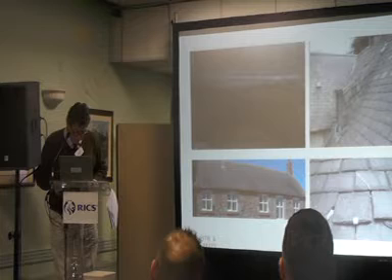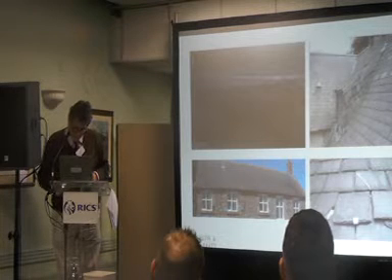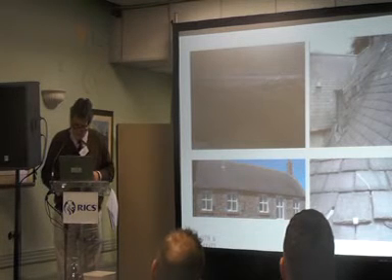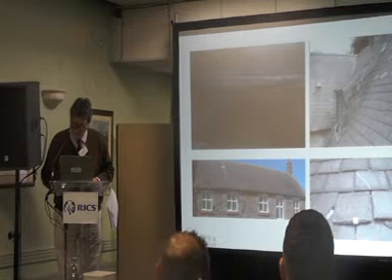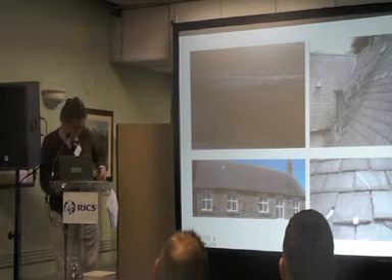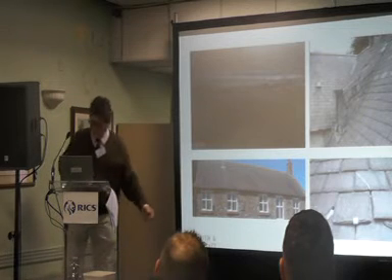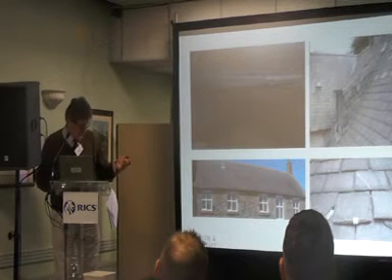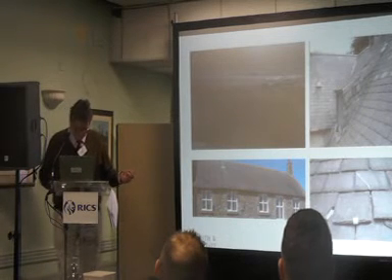And then a roof, this kind of roof, the bottom right, the kind of roof we see very often, it's been patched up, we've got mastic and we've got tingles. So this little tuck of lead here, that's pinned a little higher up and is used to hold a loose slate in.